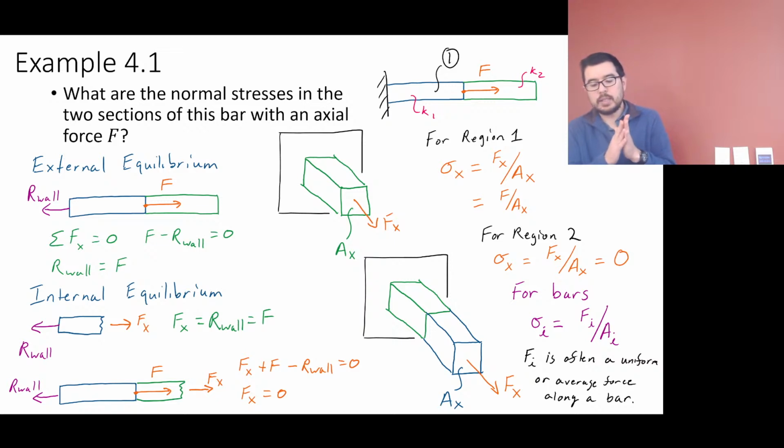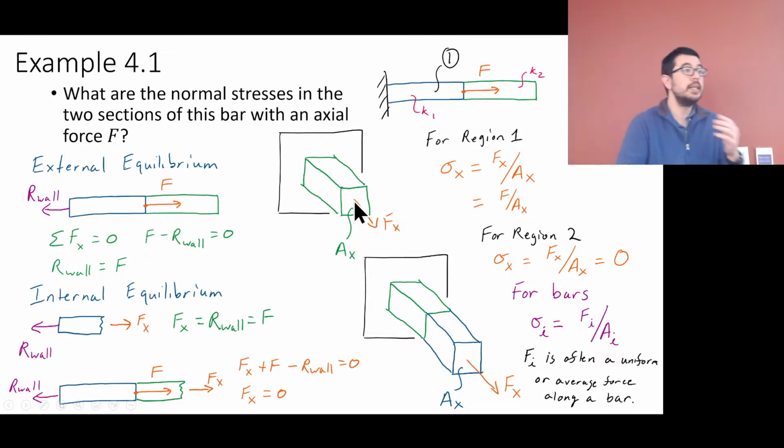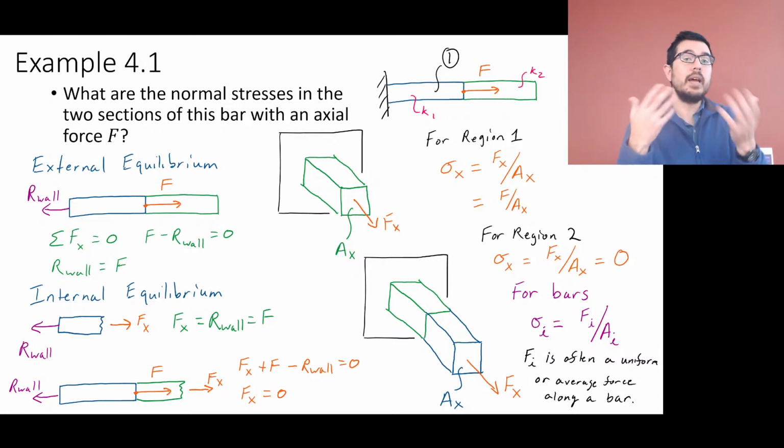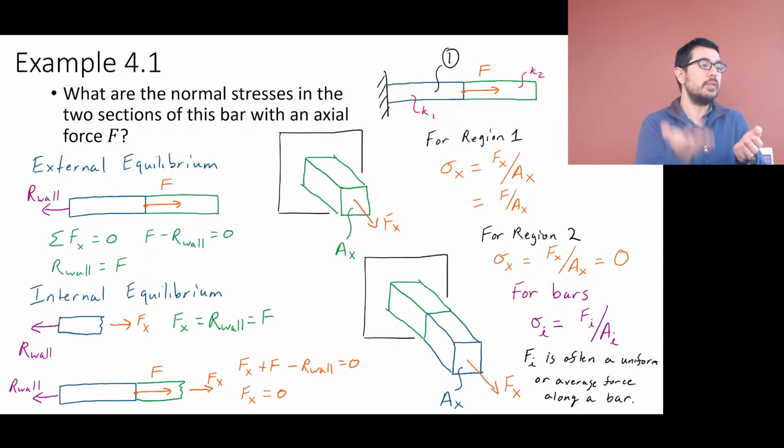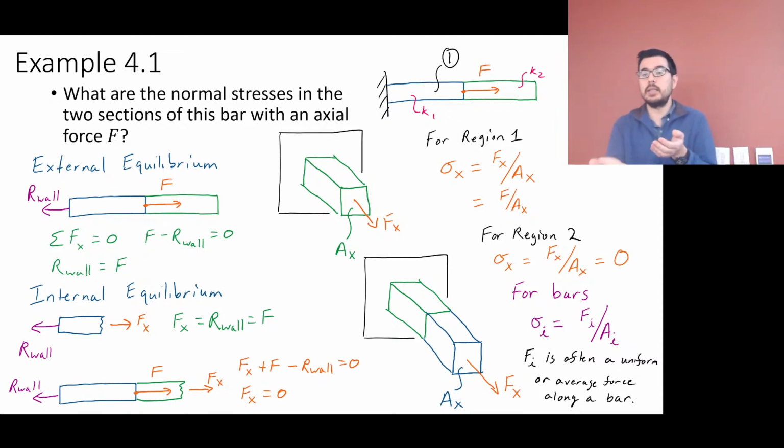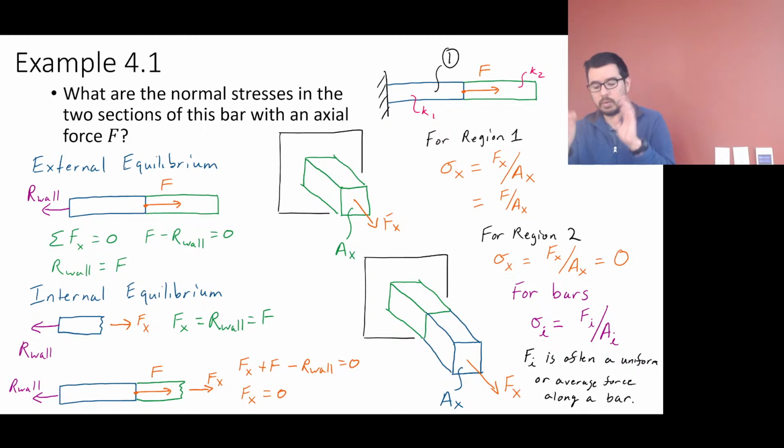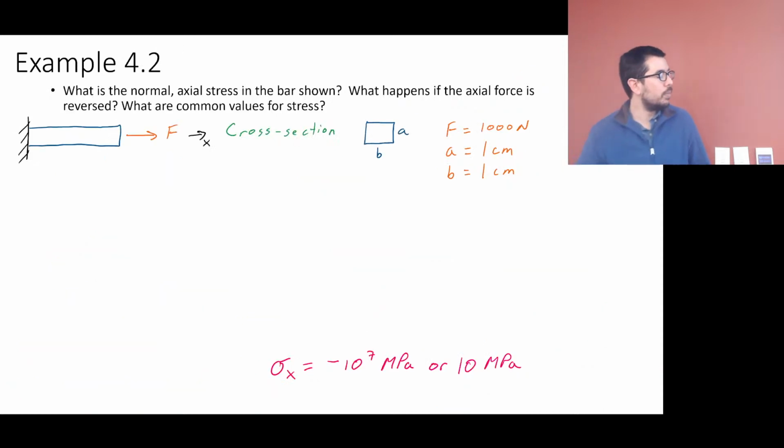So you could see systems where you have a resultant force. For example, when we do beam bending, we're going to have this shear force, or this bending moment. Like a shear force on a beam, when I draw the V down and solve for it, that's like an average force. It turns out that the distribution of stresses on that surface depends on its distance from the middle, or the centroid, or the other terms we'll introduce, such as longitudinal or neutral axis. But let's go on.